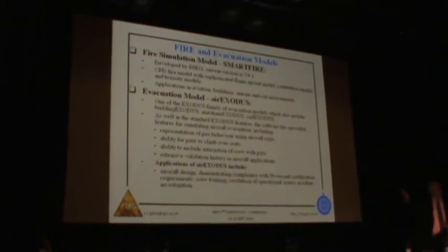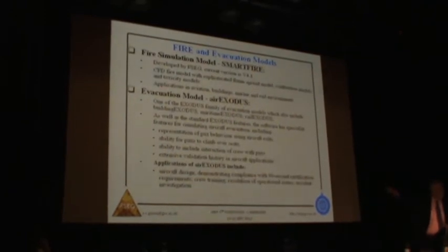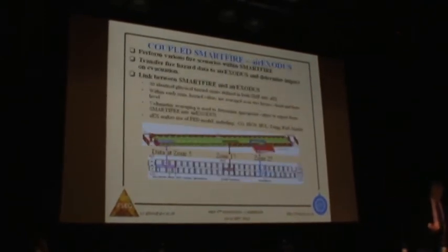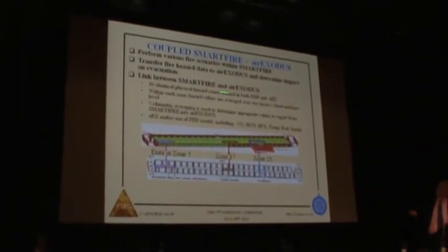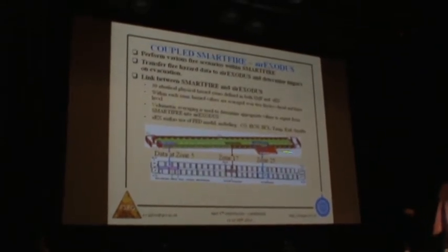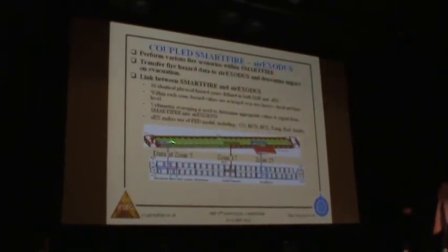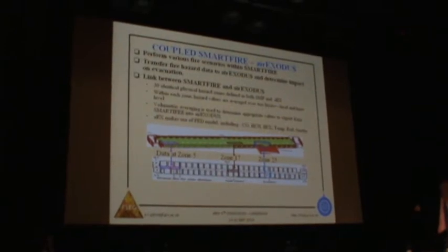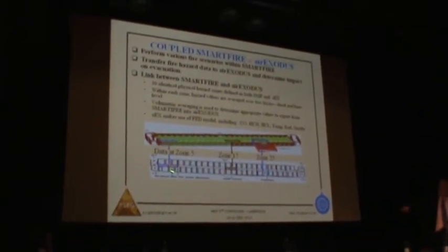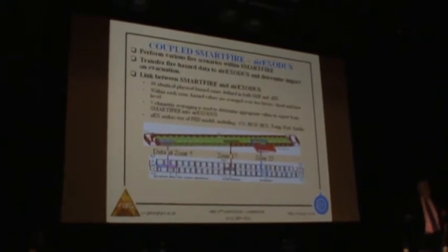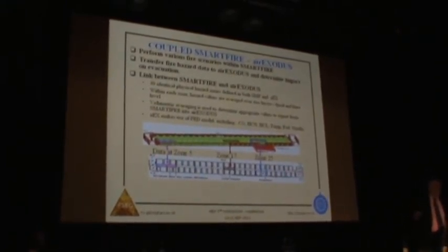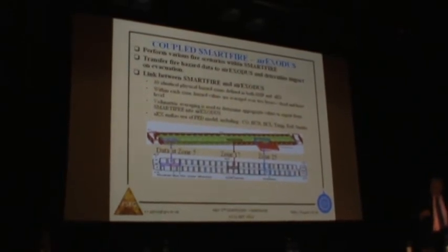And again, the motivation that I had for doing this was to try and understand this fire and understand why so many people perished in it. I'm not going to go into the details in this. You can see some of this in the paper. Basically, in the CFD model of the aircraft fuselage, we split this up into a number of zones, and we average the CFD data for the temperatures, the smoke concentration, the toxic gas values, and so on, and transfer these averaged values into the evacuation model, into these zones. The agents that are moving around then react to the toxic hazards using fractional effective dose models and behavior and smoke models, and so on.